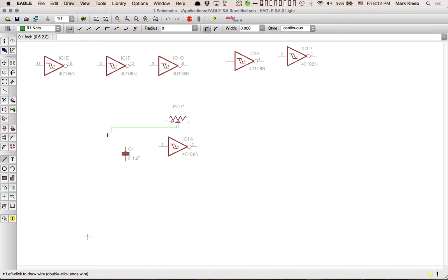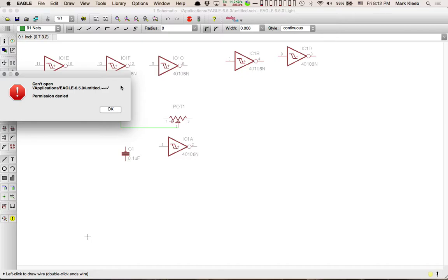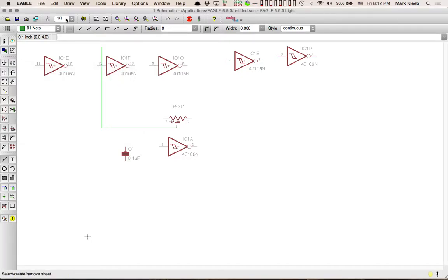Now, as soon as I click, this wire will follow my cursor everywhere, right? So if I want to make this wire super long, I can do that. It's also only going to angle at the top of the screen. So see here, I only have a 90-degree angle selected. I can select these different styles of bending. I can have curvy and S-shaped bends if I want as well. Here on the schematic, it doesn't really matter. This is just kind of for your own documentation, but when it comes to the board and drawing traces, changing your angle would be pretty important.